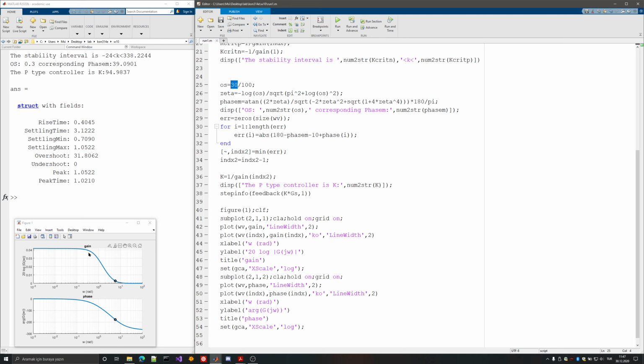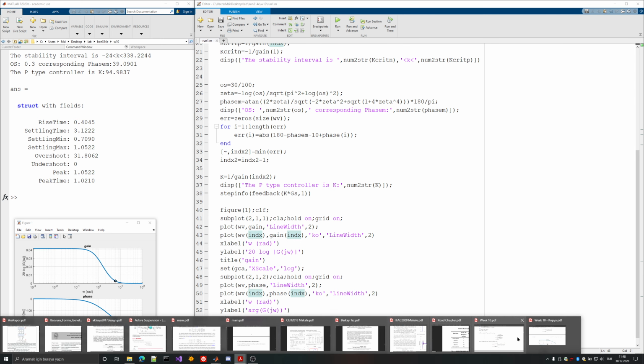You will use both the frequency and time domain approaches because we're at the stage where we're trying to learn these methods. But in the real world, if you're trying to apply them, then this rule of thumb is very important. If you have a model, if you have a detailed model, go ahead and use time domain approaches. If you have an idea, a Bode plot, a frequency plot, some data that is not exactly describing a transfer function, then you can just go ahead and opt for the Bode option, because you don't have a transfer function. How will you come up with a dominant pole pair and try to design for settling time, overshoot and all those specifications? So basically, this is trying to show you.